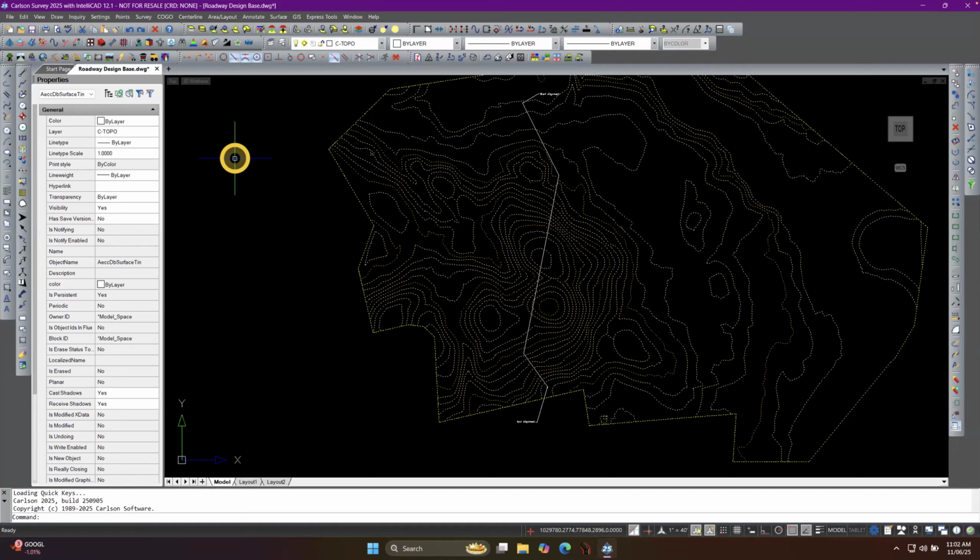And there's several other things that you can use to get at the data that's in here. Because if you're familiar with Civil 3D, and to be fair, other software also does this, it creates surfaces but keeps them as part of the drawing file itself. It's an embedded, what they call an extended entity. But Carlson, on the other hand, in contrast to that, and it's a conscious choice, they store their information externally to the DWG file.